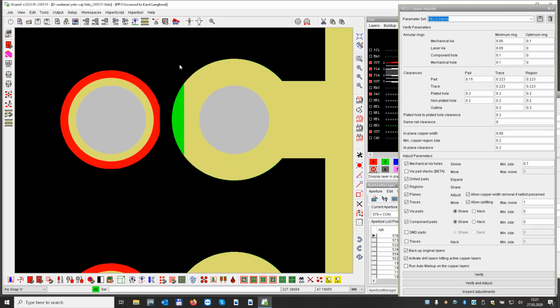We did not enlarge it on the other side because it's a huge ring already, it's very big. But this pad we enlarged, and afterwards to ensure that we have the correct clearance, we shaved the surplus amount of copper. So we have now a perfect situation. We have the biggest ring that we can get, and we still have our clearance. Okay.